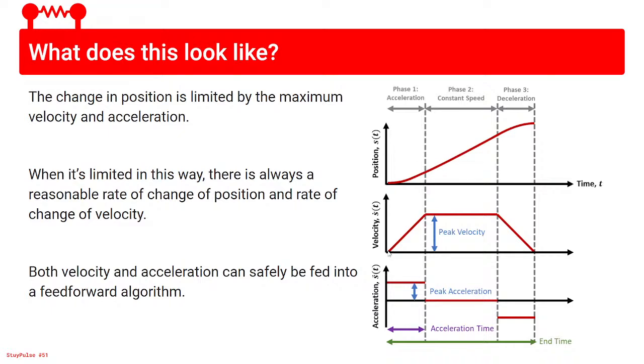It's no longer a giant spike. It's a trapezoid, because you have your velocity increasing, you reach your maximum velocity, and then you decelerate. And the acceleration is also not a giant spike. I didn't show the giant spike before; it would have been like 2 spikes. But anyway, this graph makes sense because you have your max acceleration over here. Once you reach your max velocity, you no longer need to change your velocity, and because you're not changing your velocity, your acceleration is 0. And then once you decelerate, it's negative the maximum.